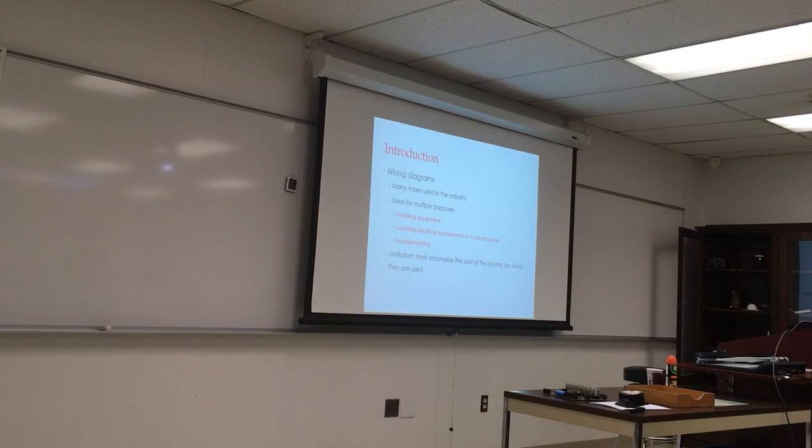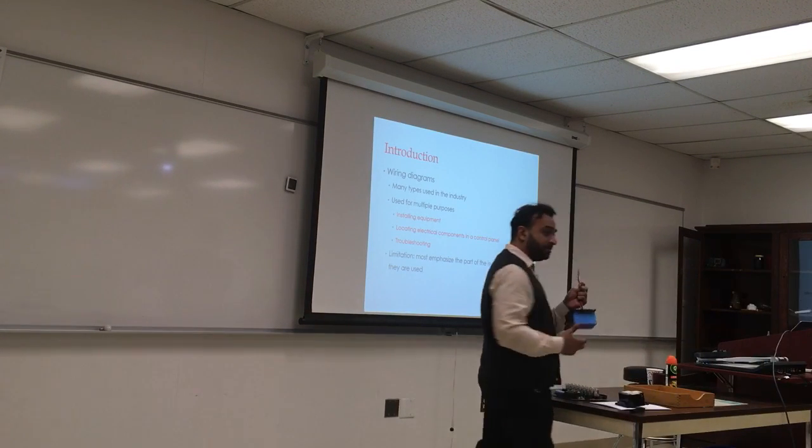Limit. What do you think limit is? Current? Shouldn't it shut down after a certain limit? Yeah, so limit usually is whether it's a thermostat, high pressure switch, or low pressure switch that will shut off the entire thing. So the whole thing is wired: if this wire is activated, then the whole equipment will shut down. So that's the limit. Remember that.